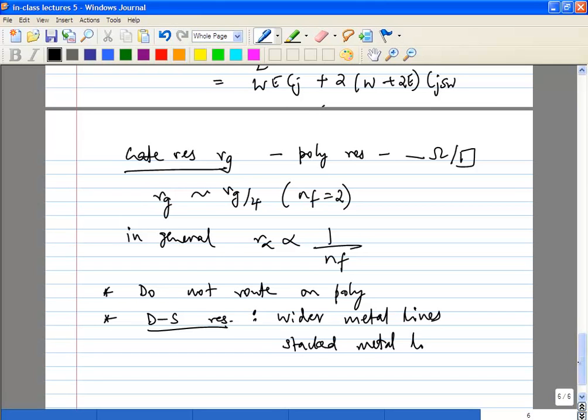Modeling means you are saying that modeling itself is not there, or just selected the wrong switch? The thing is, these kinds of parasitic capacitance may not be something. Remember that everything you extract only increases your simulation time as you do the LPE. There may be certain small parasitic capacitances which you don't care about, and certain cases where you really don't care about these capacitances.